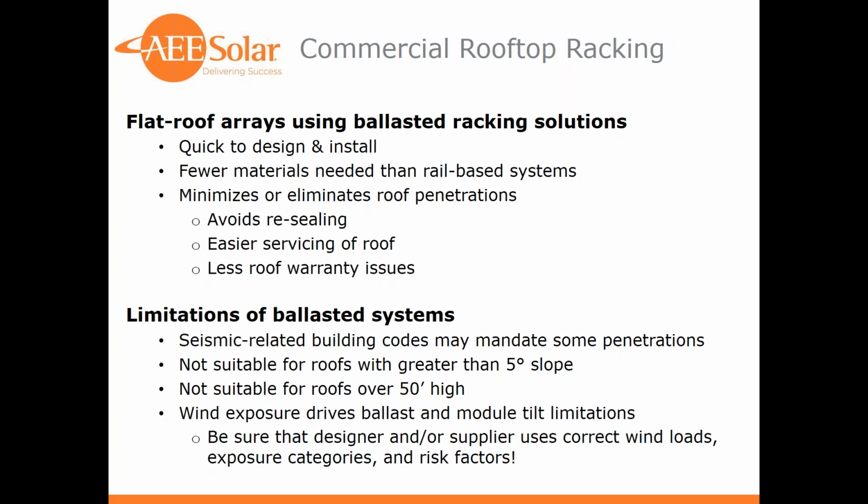But we're getting feedback sometimes that, hey, why is this ballasted system so much more than the other ones? And I go on this online tool and it says they're not, because you're potentially not using the correct wind and exposure categories, or don't have the right building heights in there. So please be sure if you're using an online tool to estimate that you do get the right jurisdiction required wind and snow loads.